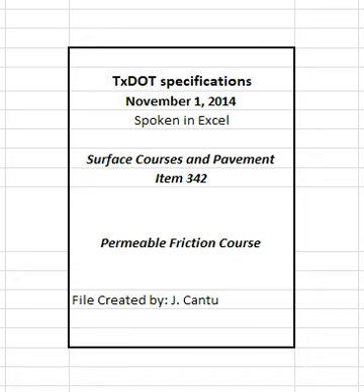4.6 Hauling operations. Clean all truck beds before use to ensure that mixture is not contaminated. Use a release agent, when necessary, shown on the department's MPL to coat the inside bed of the truck. Use equipment for hauling as defined in Section 342.4.7.3.3, Hauling Equipment. Use other hauling equipment only when allowed.